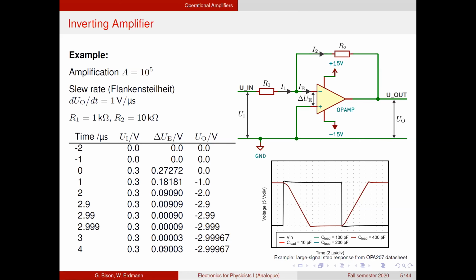Now this, together with the gain factor, gives us an output voltage that is given by this value, which then in the voltage divider exactly calculates to this value. So this is where the op-amp is stable now. So we see we need a tiny difference voltage on these two terminals to generate a sizable output at the amplifier.